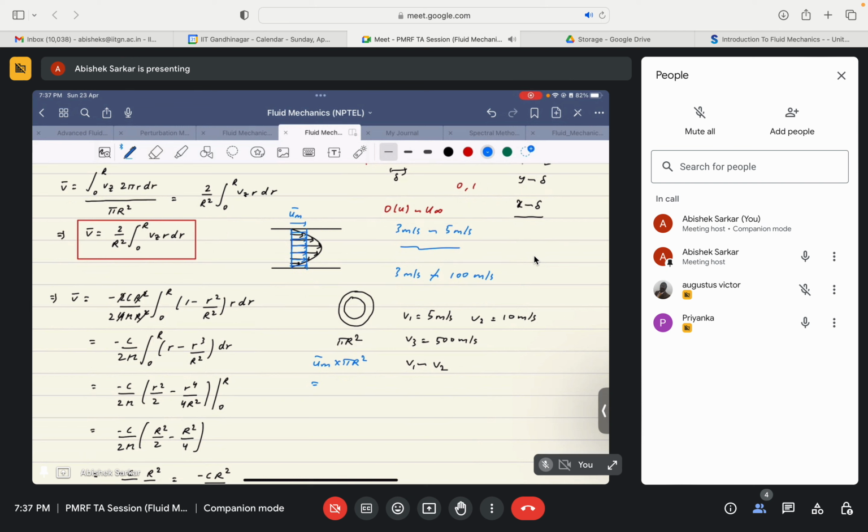Why is it not valid? Because of the boundary layer. Yes, because of the boundary layer, basically because of viscous effects, and most importantly, to be more clear, because of the no slip boundary condition. So the velocity at the boundary walls should be 0. So the black one should be our velocity profile.